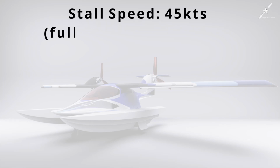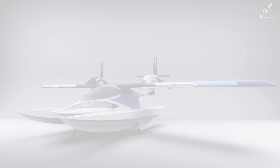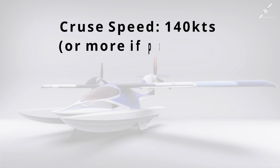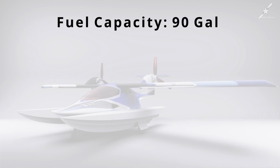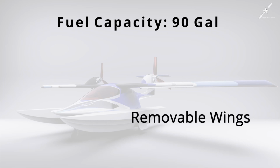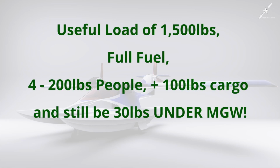A stall speed of 45 knots, full flaps power off, VSO. A cruise speed of 140 knots or more if possible. VNE speed around 200 knots. Fuel capacity of 90 gallons, which is located inside the fuselage, allowing for easy removal of the wings. This means with a useful load of 1,500 pounds, we could have full fuel for 200-pound people plus 100 pounds of bags and still be 30 pounds under maximum gross weight.